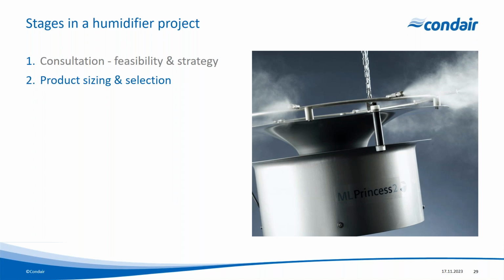And when we size a humidification system, we do this based on the amount of air that we're humidifying. So we would look at the space and the type of building, and then we'd ascertain an air change rate typical for a building of that size and how leaky that building is, and how many doors are opening, what's the door opening frequency, and how big are the doors, etc.